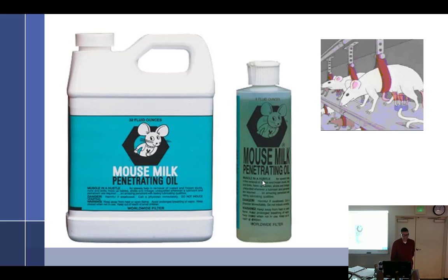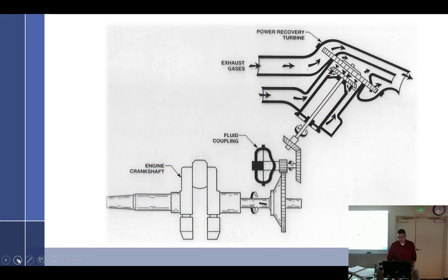Lawrence knows that. Yes, I do too. So mouse milk is the lubricant that you're going to want. I do it on every annual on turbocharged engines and really lubricate that wastegate so it works nice and fluid, and all the fittings around it. And so, mouse milk, and we're going to write that down.